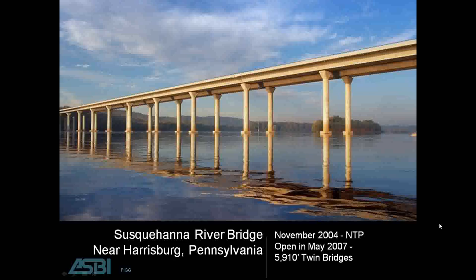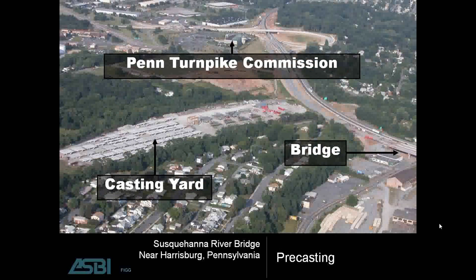So what we see is, in many cases on these newer segmental bridges, especially up in the areas where de-icing chemicals are utilized, we see the application of the integral wearing surface, which once again is an additional 2 inches of concrete on the top slab that can act as a barrier for chloride intrusion. Concrete segmental was chosen once again for durability reasons.